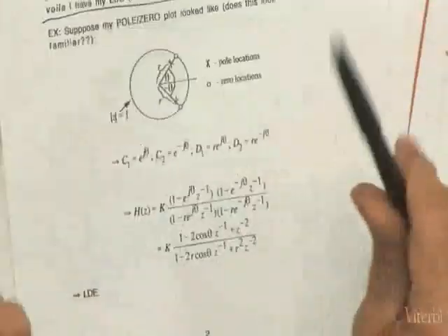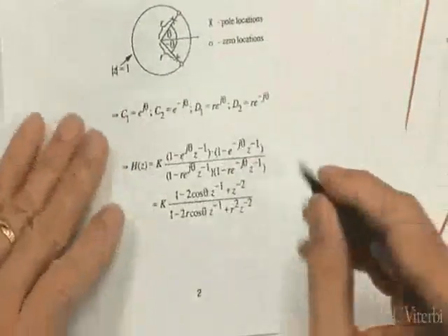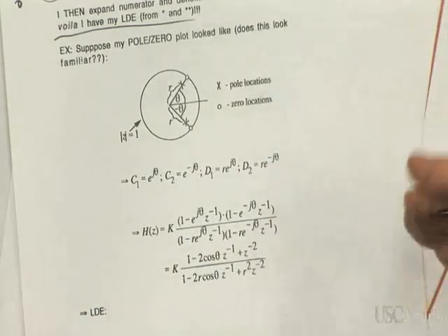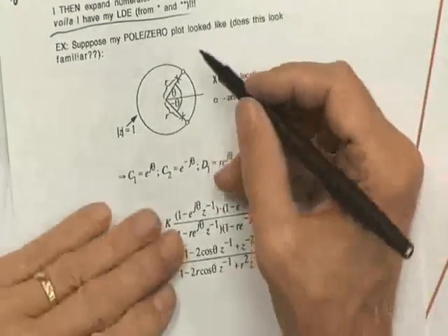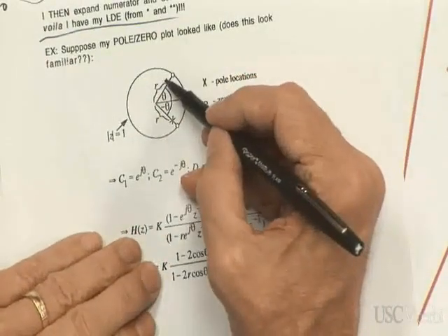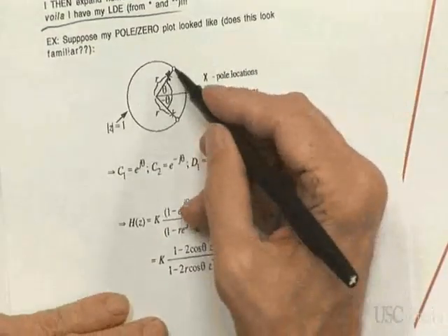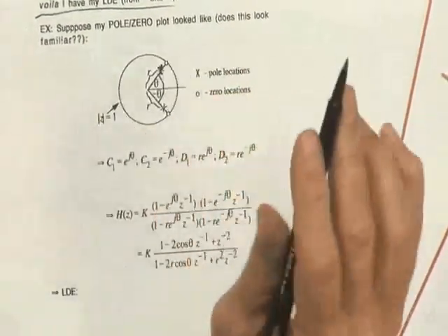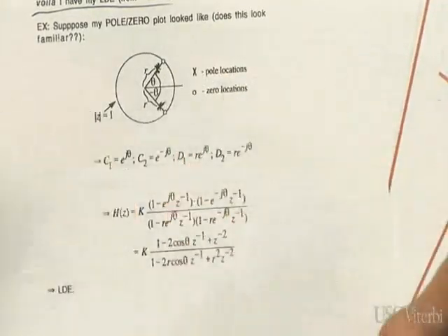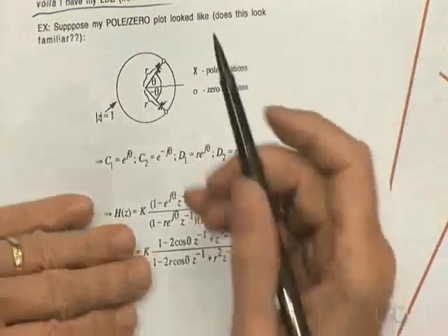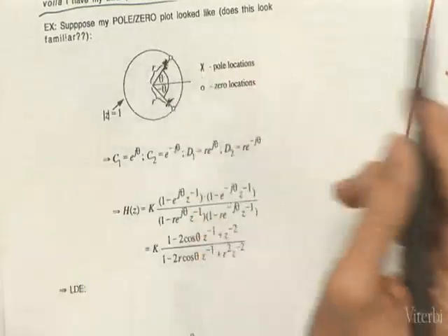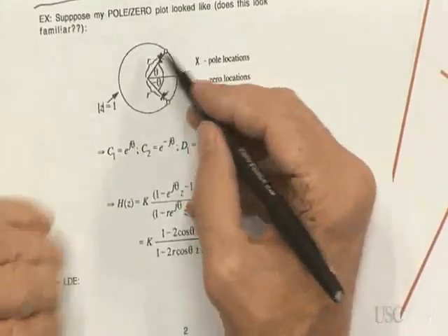Okay, so here's an example, like the project, where I give you 2 poles and 2 zeros. Now, the poles, interestingly enough, not the zeros, but the poles are these x's. Kind of hard to see this. But they will be inside this circle. That's a unit circle. The poles will be inside the unit circle. This is a causal system, so that's good, because we know that the region of convergence will be exterior to these poles. And guess what that region of convergence is?